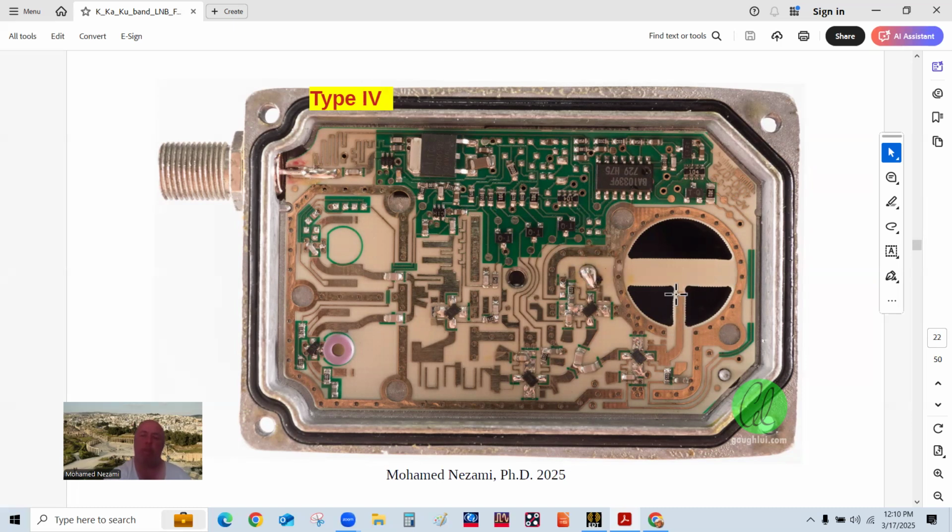At the same time, the other pole is right here, and the cap that comes and covers this, I'll show you a picture of that in a second, acts as a short back end for this one in here. And of course, both of them have a low noise amplifier, and in this particular design they have a single stage of amplification for either one of them. And then they join each other and go combined into another LNA, and then into a hairpin filter, and then onto a mixer, okay?